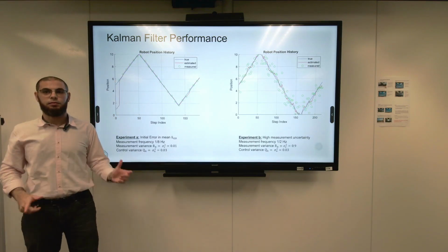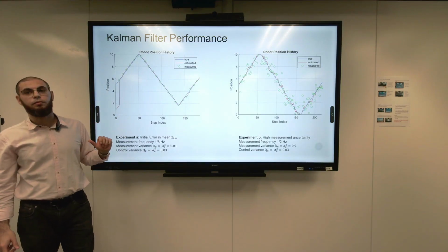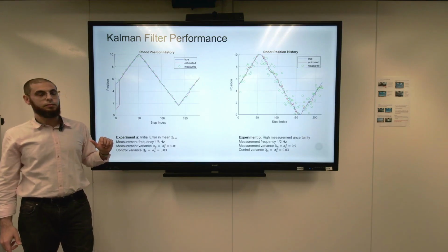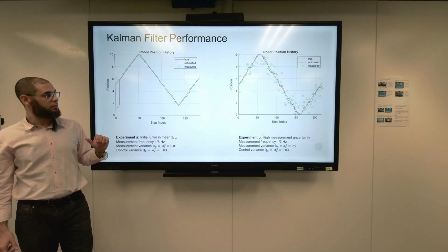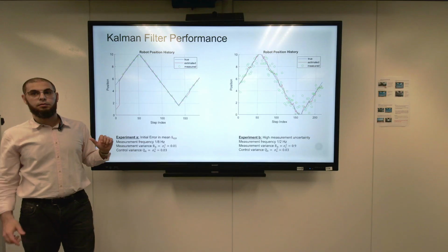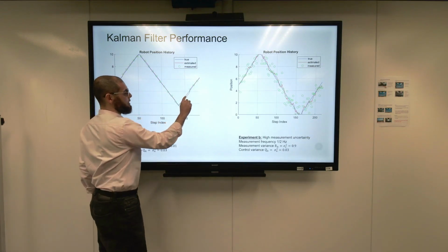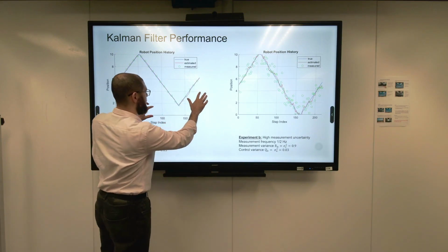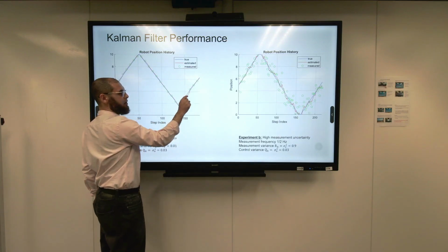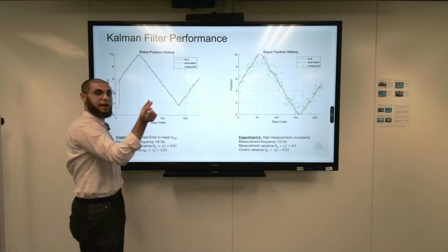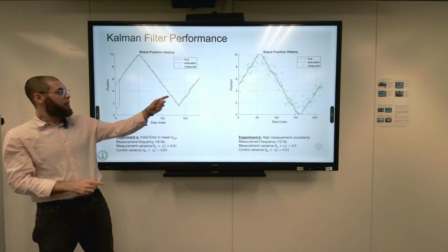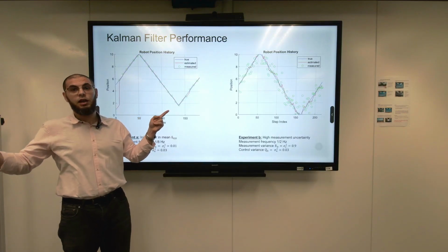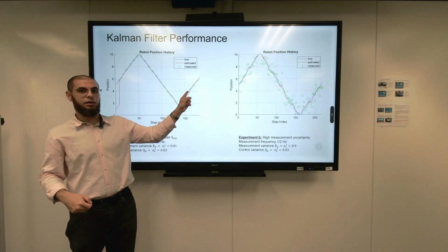But look at the prediction, the projection of the line. It's going for 8 seconds unknowingly. It doesn't know what's happening. That's correct. But it's going for it until it gets the second measurement after 8 seconds. And that's why in this case, you started to have an error. For example, take a look. I cannot zoom here. So you see what's happening here? This is very clear, right? Between this measurement and this measurement, you have a big error, and it's not being corrected. But after you get the measurement, you jump very high. You forget that you have this prediction, and you're trusting more the measurement. So that's what you see here.